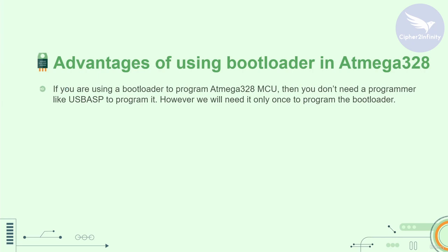So the first advantage is, if you are using a bootloader code to program the Atmega328 microcontroller, then you don't need a programmer like USB ASP to program it. So we don't need the USB ASP programmer at all. It will be completely eliminated once you have the bootloader code in the microcontroller.